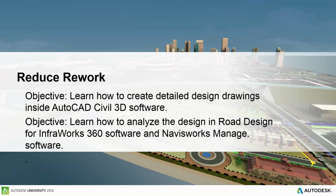Beyond that, we'll also want to analyze the design, and we'll use Navisworks Manage software to analyze the road design compared to Revit model, maybe from the architect, and we'll combine those two together in Navisworks so that we can do a clash detection and make sure that everything is coordinated properly.